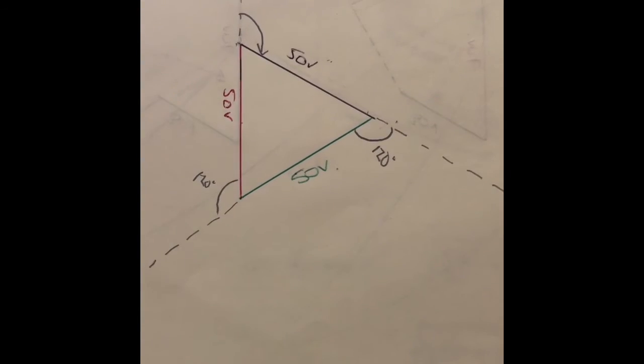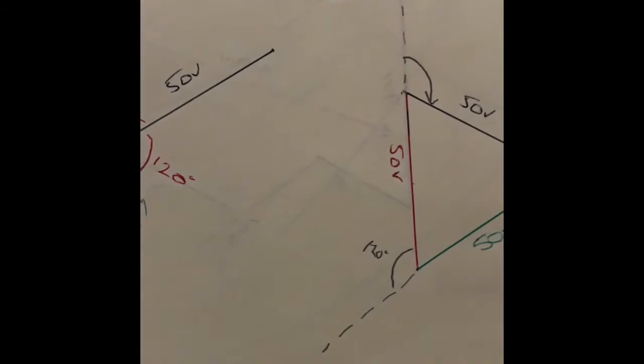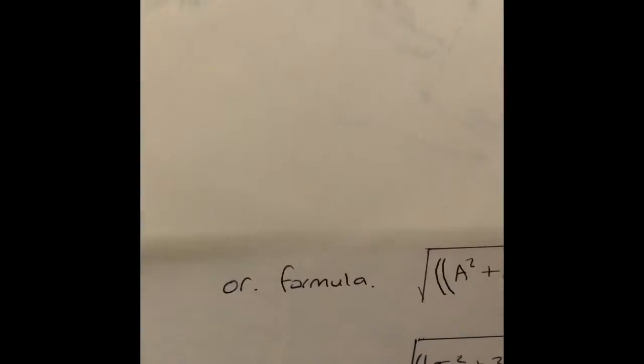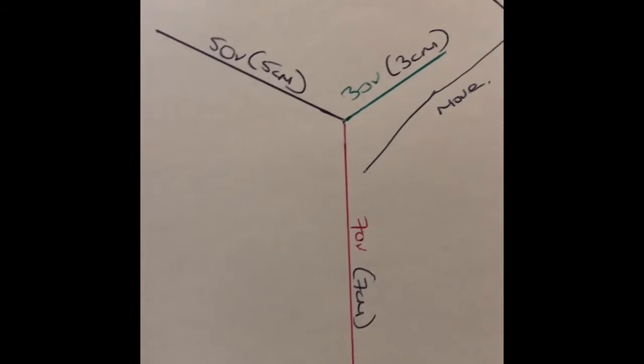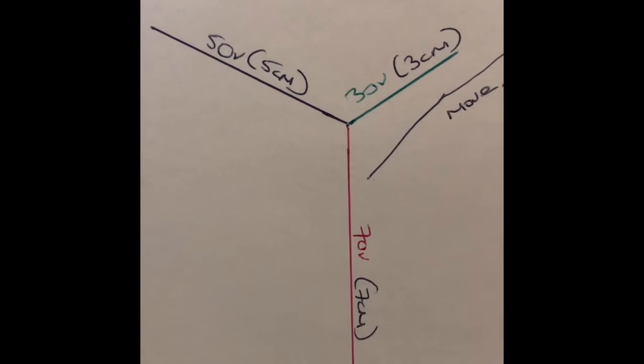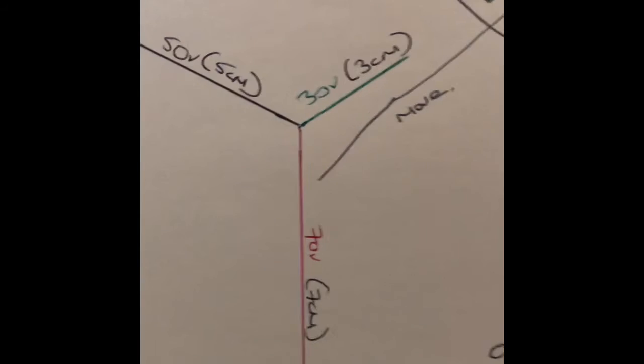So from this image, I'm now going to try and transfer it over to an unbalanced system to give you a little more understanding. The next page is quite busy, so please bear with me. I will try and go through to make sure that we can grasp any of the information we need to. From here, I've basically gone back to a star system, and I've scaled this out as much as I can. This is a 3-phase. I have written, for some reason, single phase on the worksheet. Just completely ignore that. This is a 3-phase unbalanced system.